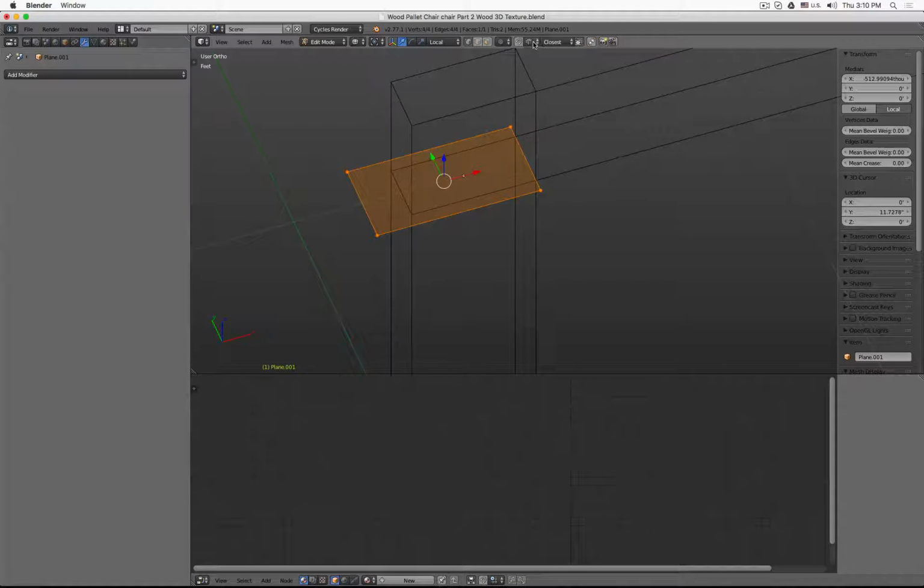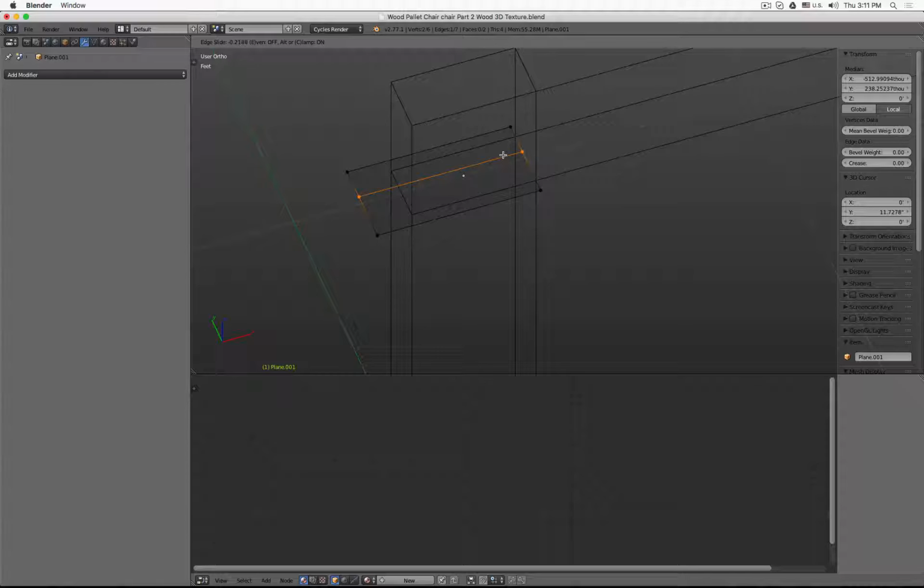Oh, I snap actually to the edge. Maybe K. See, that's okay. So when we do the knife tool, if we want to snap to the midpoint, have the vertex maybe selected. K, Control, click, and click. That's one way. Or we can press Control R, select this edge. You see now we can move it, and then we press 0 so that it's in 50% position, and press Enter.